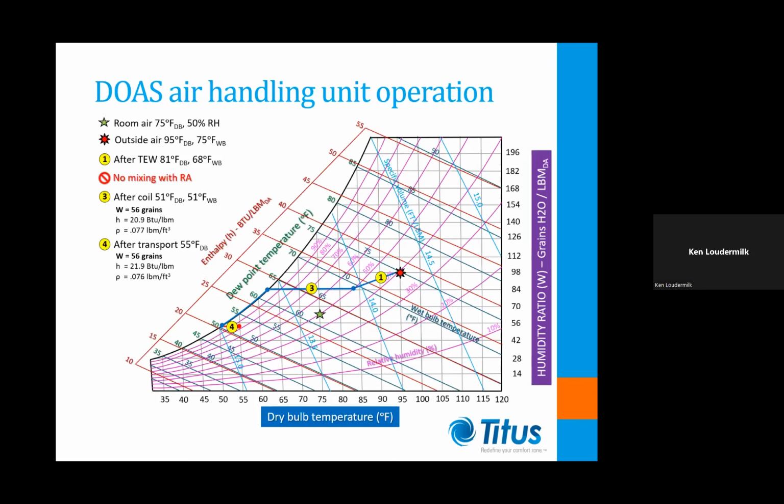And this may result in reductions in that airflow rate of as much as 2/3 versus the mixed air or all air type system. Finally, the air leaving the coil is subjected to sensible heat gains while passing through the fan motor and downstream ductwork, as we saw before.